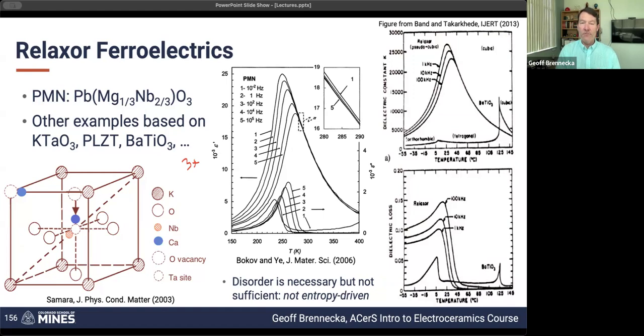So the first step is, if from an ionic radius perspective it can go on either site, then we say, all right, what would it mean if the valence is the same, but on this side it's a donor and on that side it's an acceptor? It gets more complicated if you have something like tin or bismuth, where technically they can change valence as well as site, and now things get a little bit more complicated. Fortunately, within the PZT system, at least, tin always wants to be on the B site, but it is possible to make tin A site perovskites. They're just hard to stabilize. So hopefully that answers your question, Gabrielle.